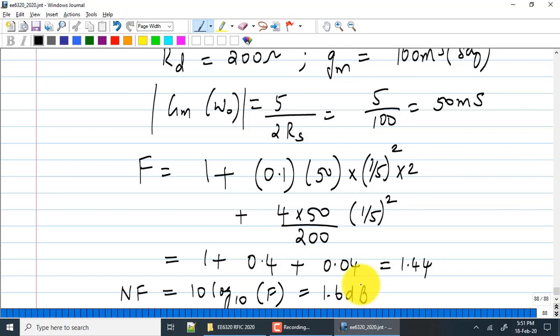What is the disadvantage of this? Narrowband. Now, just remember that this particular LNA gives you very good noise figure because of what? Why does it give you very good noise figure? I mentioned this in passing. Noiseless input match. Anything else? Apart from noiseless input match, after you have done noiseless input match, you are getting passive gain through the input matching network. I mentioned that once. You get a gain of Q in.